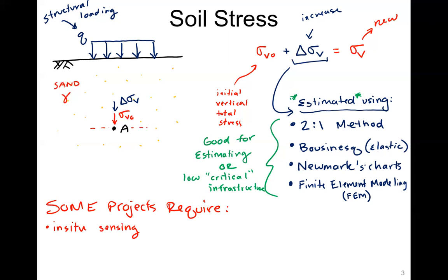So instead of estimating at point A right here and using these fun equations in math to try to understand what the stress conditions are down there, there's going to be some projects, and hopefully, if you're working on these projects, that means you're getting paid more money. So hopefully you guys get a chance to work on these, but some of them will actually require installation of sensors and equipment that will physically measure the loading and stress conditions at that depth. So some require in situ sensing, then monitoring over time, and analyzing of actual stress.